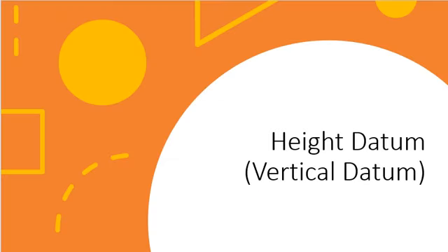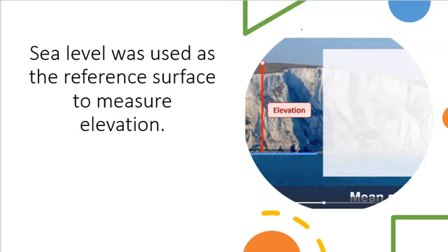Height datum is important when you work with elevation data. For years, there has been a question of how elevation should be measured. Where is the baseline? Where is the base surface to measure elevation? Let's call the base surface or the baseline the reference surface from now on. Many years ago, sea level was used as a reference surface for measuring the elevation and altitude.